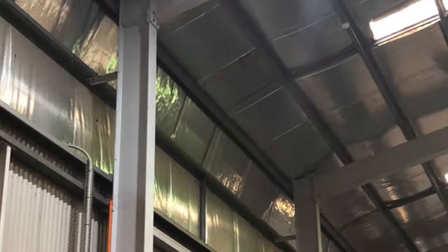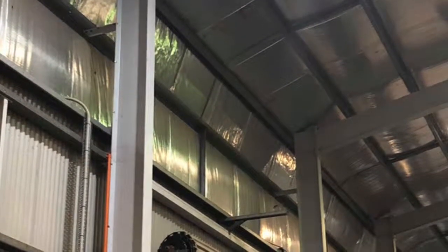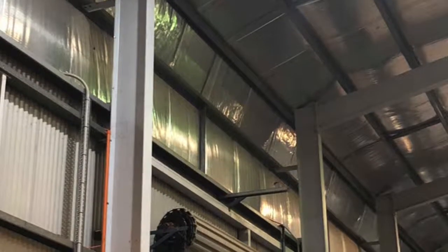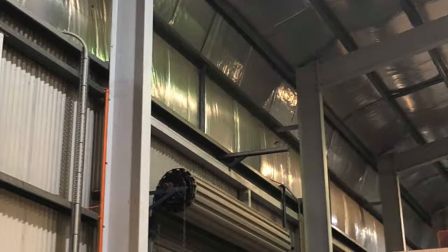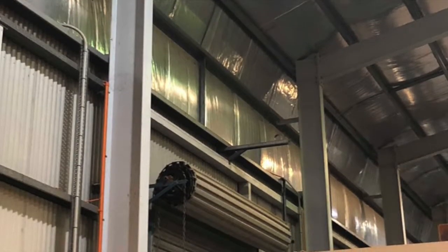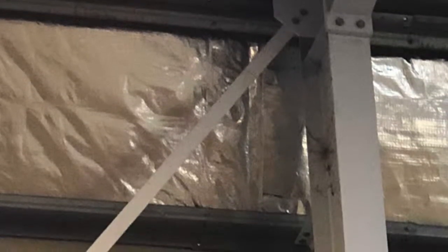Fixed to the rafters are purlins. These members are horizontal structural members that run parallel along the rafters. These provide a base to which the roof sheeting can be fixed. Furthermore, adding to the strength of the roof is bracing. This is commonly known as speed bracing, is pre-tensioned and can be applied in either an X or V pattern. The purpose of bracing is to prevent buckling and rotation of the rafters under the weight of the roof, wind uplift, and in some cases ceiling material.